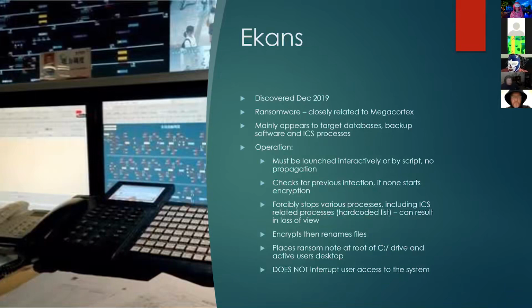Andre, are these ICS air gaps passed by human error, social engineering, missing security patches? There's a number of ways to get past them. A lot of them are because air gaps are never truly air gapped. You have to move stuff in order to either add equipment or update software, or update the programming, or get data out. So you keep it as gapped as you can, but it's never 100%. So you try and be as vigilant as you can.